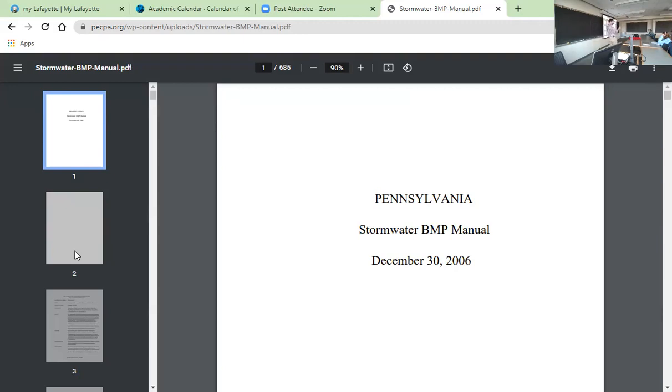Because if I pave an entire area for a subdivision, for a road, am I going to generate the same amount of stormwater as I did before? What's going to happen to the volume of stormwater? So we need to account for that. That's what post-construction stormwater is.